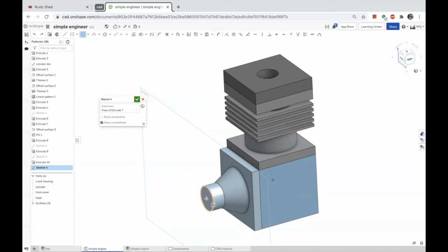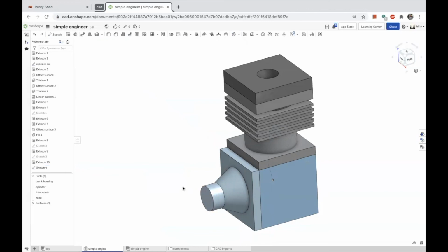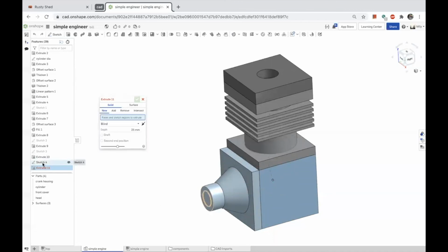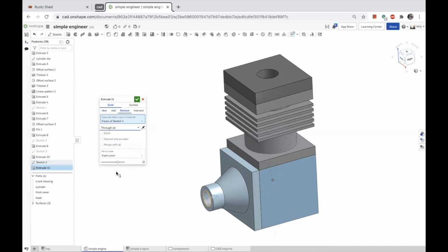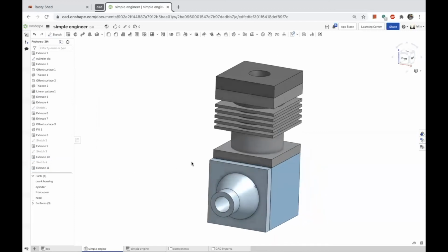I'm going to work off of this edge. And therefore, I'm going to be concentric with the edge. That makes sense. I'm going to put a diameter. I'm going to come over here. I'm going to paste it. I'm going to say OK. And I'm going to blast a hole through my cover. So I'm going to click sketch, go take the sketch. And let's go all the way through until you hit the outer boundaries of the part.